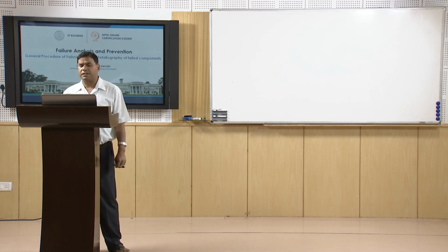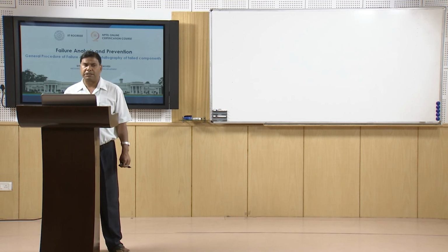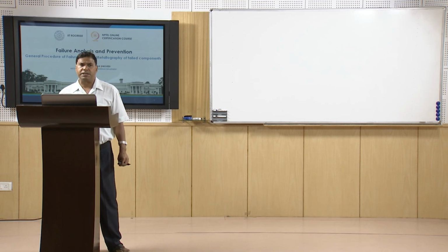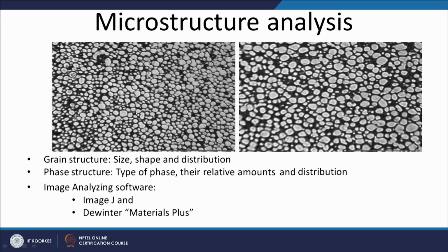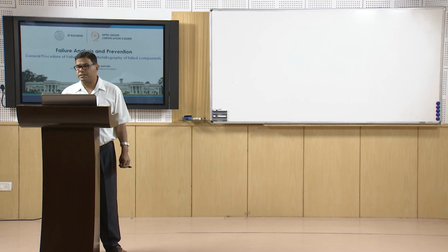So, these are some of the things which can be done as per the need, and now we will be seeing some of the microstructural aspects. Like this diagram shows that one structure is different from the other, one structure is finer than the other, and through image analysis we can easily identify what is the average size of the white constituents. This is basically a cellular structure with the eutectic matrix which is dark, and cellular grains are light etched, and we can determine the fraction and the size of the cellular grains while the matrix is dark.